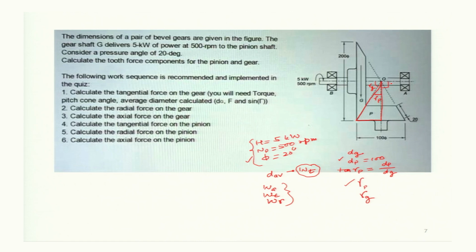So, with the similar analysis which we did for the case of helical gear, you can draw the free body diagram with reactions at the bearings and the gear forces acting at this mid of the face. You can find the reactions. So, this is the way the force analysis is done.